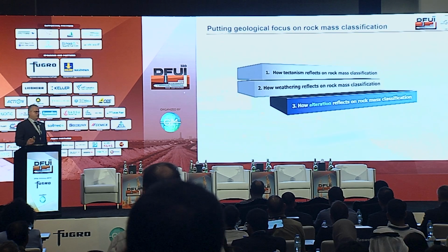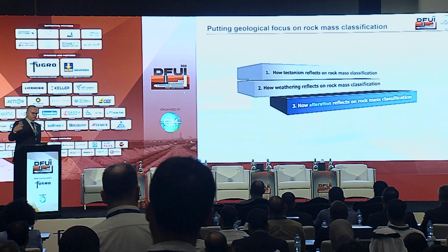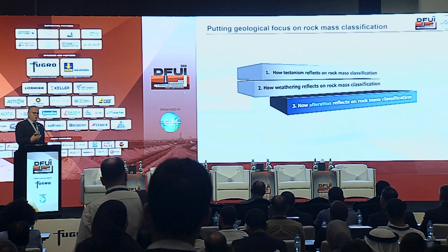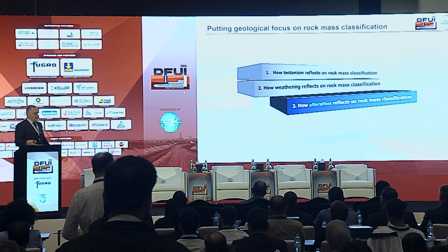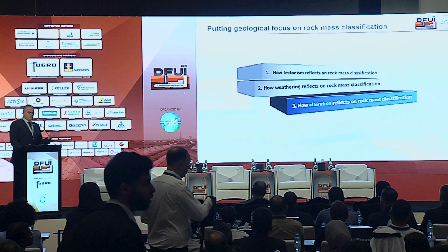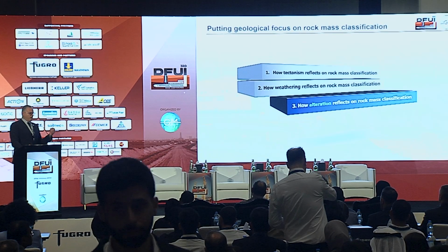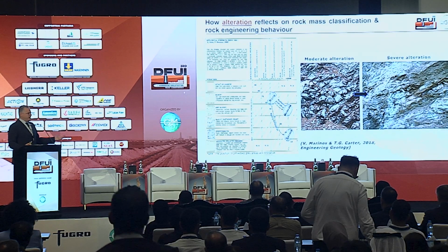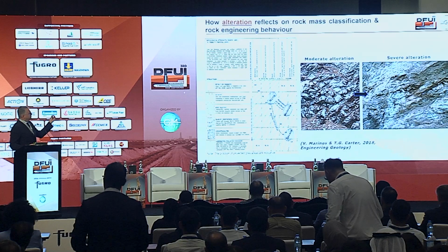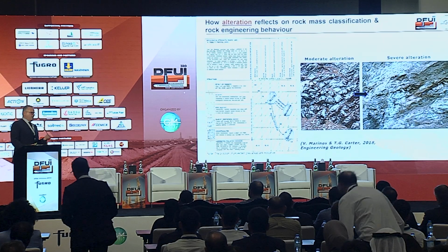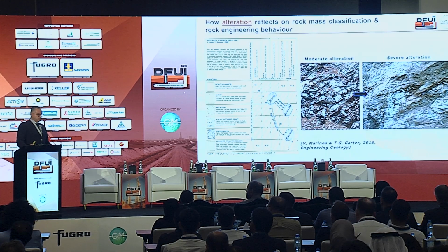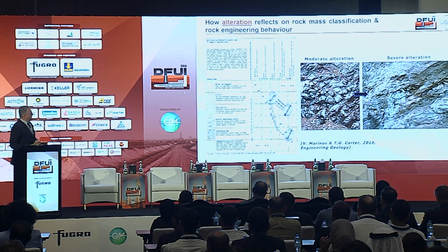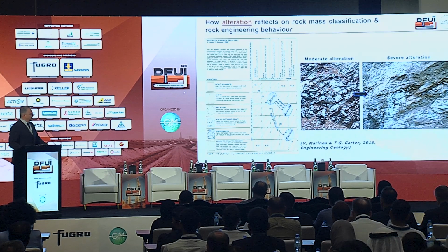On the other hand, alteration, which is another process, has to do with a movement from below the surface to the top, an alteration of the fabric of the rock mass structure due to hydrothermal processes or metamorphism. For example, here, ophiolites, you see how the rock can be transformed into more clay-like zones or highly serpentinized rock that dramatically loses the intact rock properties.